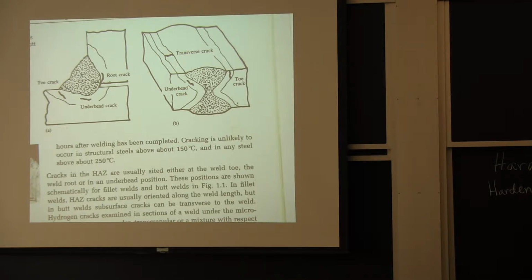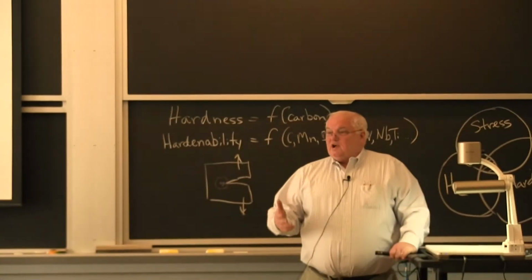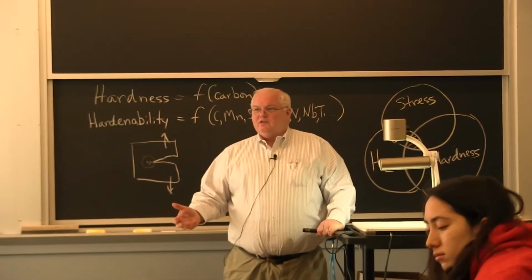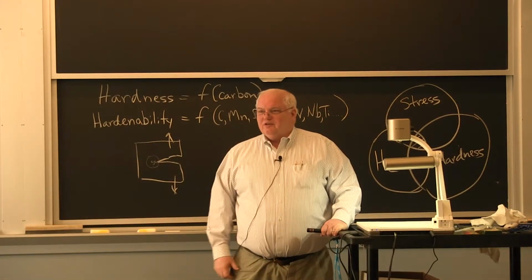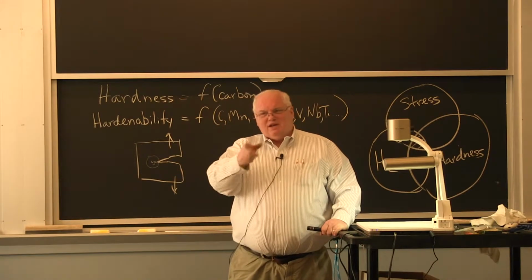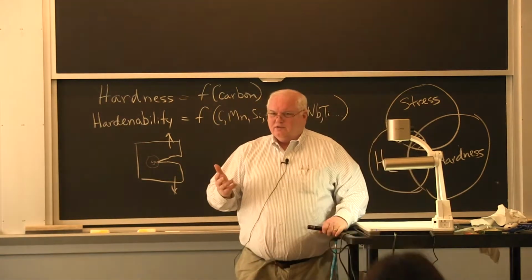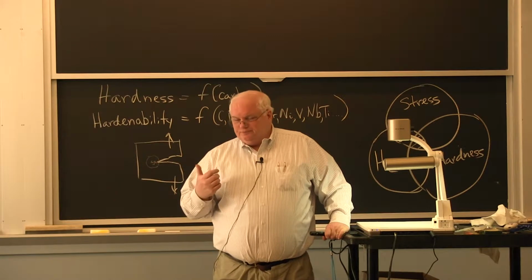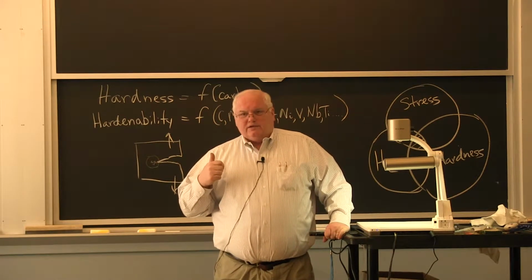It still occurs frequently, okay? I get several hydrogen cracking problems thrown at me each year because we know about it, we know how to control it, but that doesn't mean that people do. Now, where does the hydrogen come from? What's the largest source of hydrogen in the world? Water, the ocean, okay? It doesn't come from the ocean, but it does come from moisture, because moisture's everywhere too. So it turns out one of the key areas is moisture.